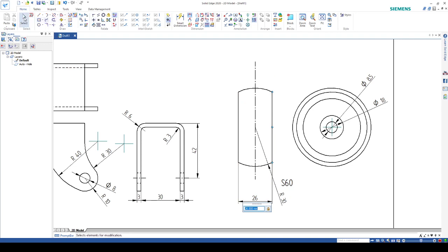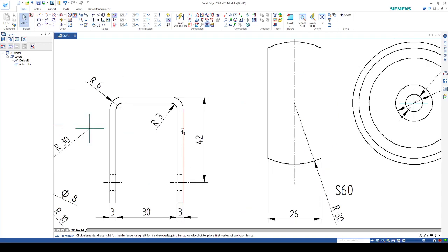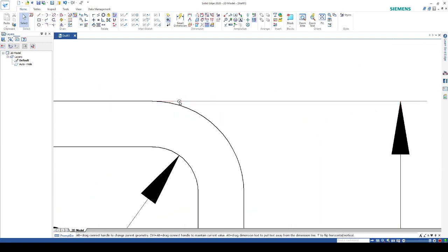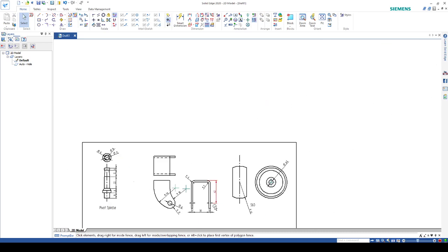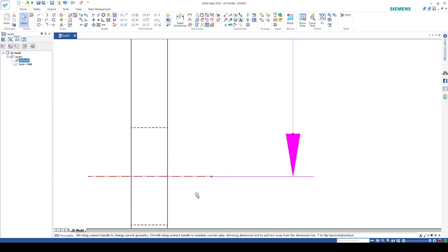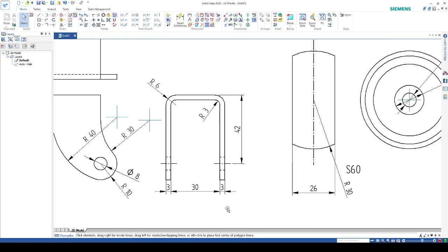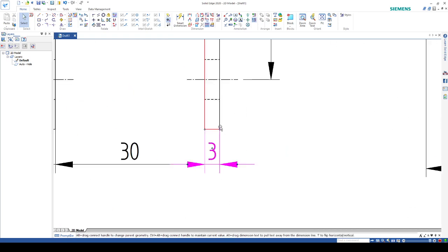Okay, make sure you read my notes on dimensioning. There should be a little gap in the leader lines, like that. So the leader lines of the drawing should not touch the picture, except for obviously those radius lines. But this one here, everyone should be offset by a couple of mil, so it's not touching the drawing.